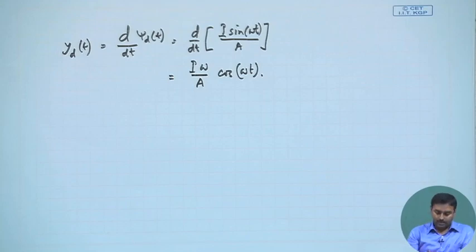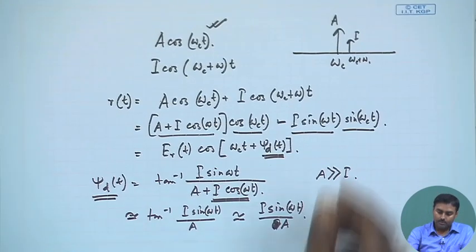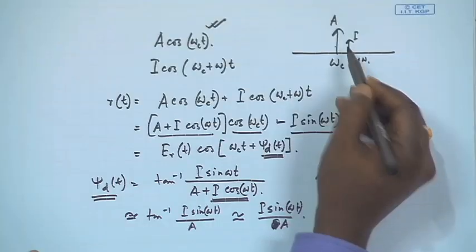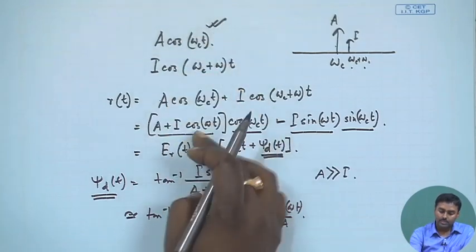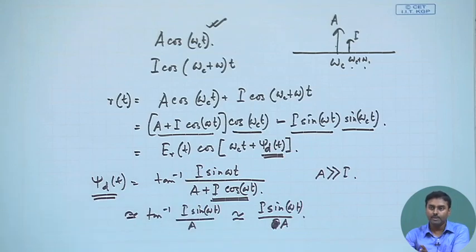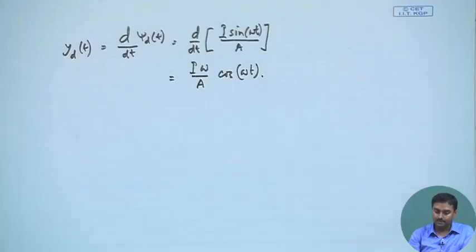So, basically, what we have done is we have tried to see the interference. We have just said that we are probably transmitting an FM signal, but we are considering it unmodulated, that means just the carrier, which we are sending for testing purposes. Nearby that carrier, within the band of FM, I have an interferer which is at omega c plus omega. Okay. So, these two signals in composite fall on my receiver. I am just trying to detect the phase the way FM does, and if you differentiate the phase, that should be the frequency variation, and that we call detection. Okay. So, this is what I will be detecting, right.